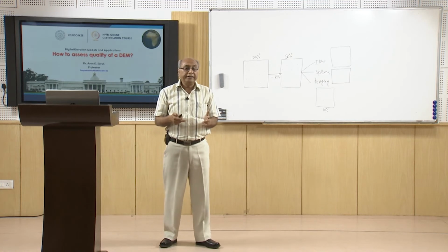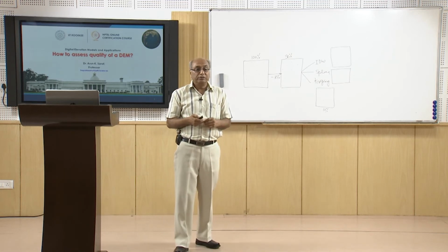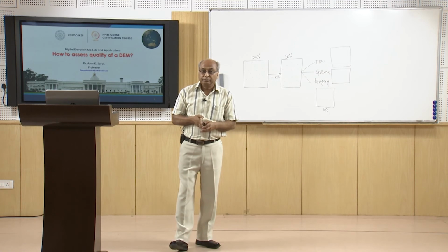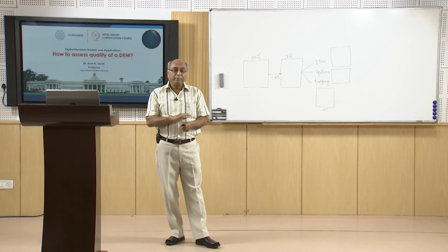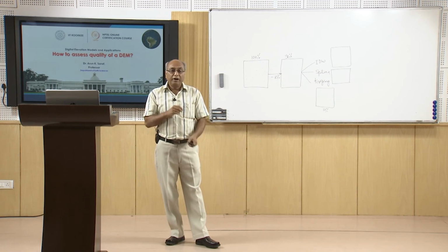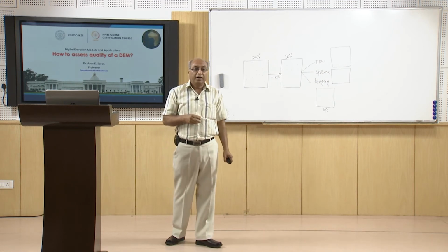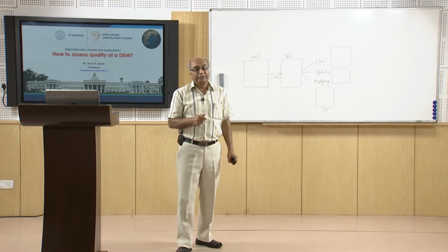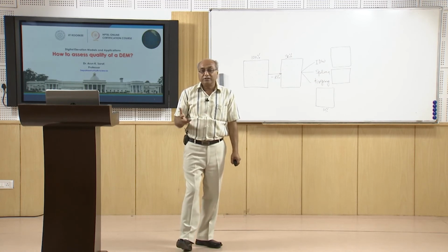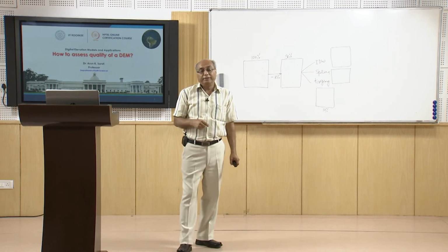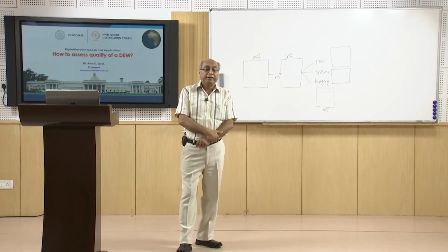And the quality of a DEM can be assessed using GCPs, ground control points, or point heights. Here it requires a little discussion. If I have a ready-made digital elevation model and I want to assess its quality, as mentioned just a few minutes back, we need some external source of data, maybe point elevation data derived from GPS or differential GPS or maybe some other survey techniques.